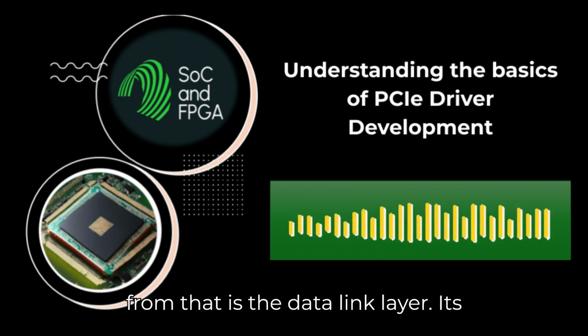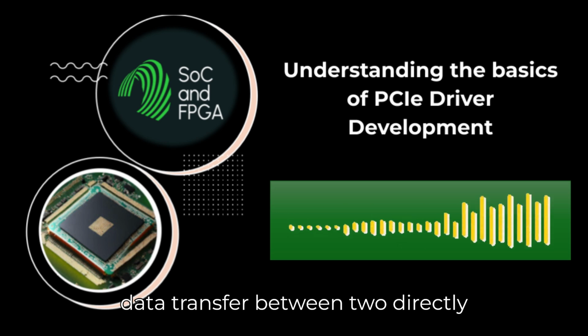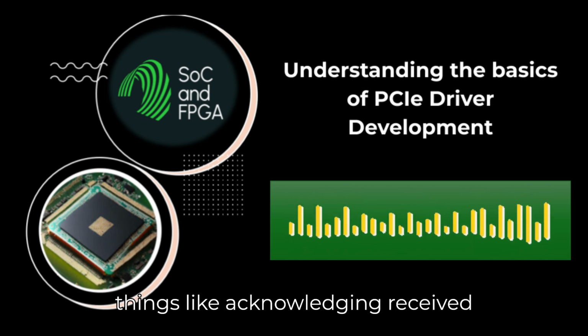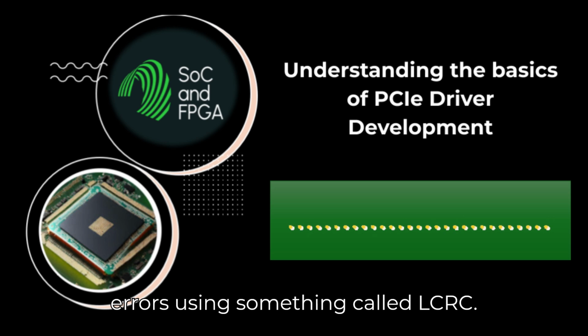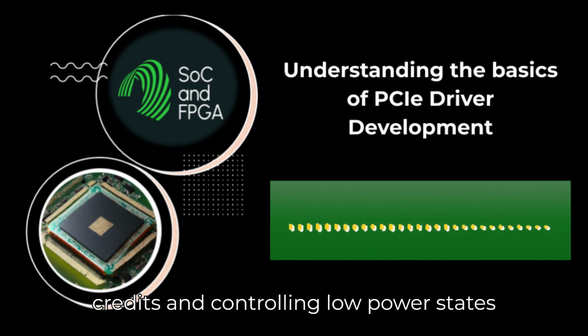Down from that is the data link layer. Its main job is ensuring reliable, error-free data transfer between two directly connected points on the link. It handles things like acknowledging received packets, ACK and NAK, checking for errors using something called LCRC, managing link-level flow control using credits, and controlling low-power states for the link.